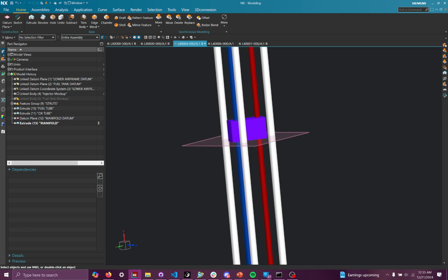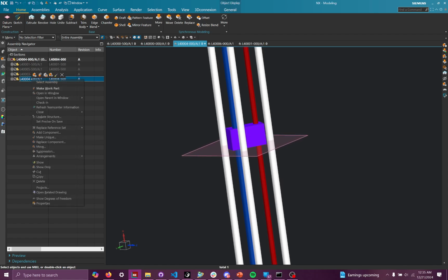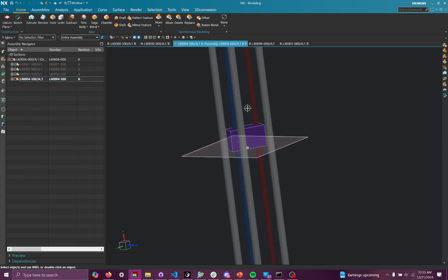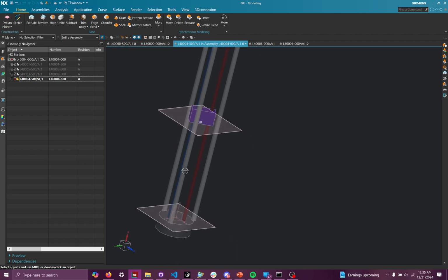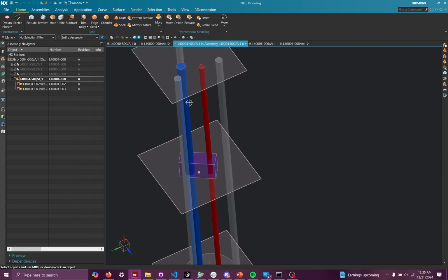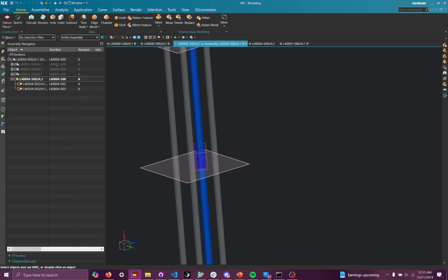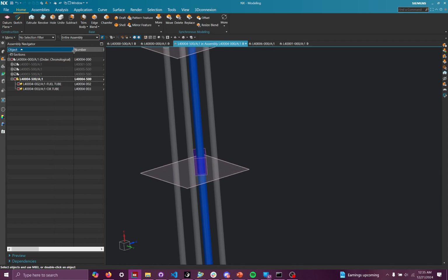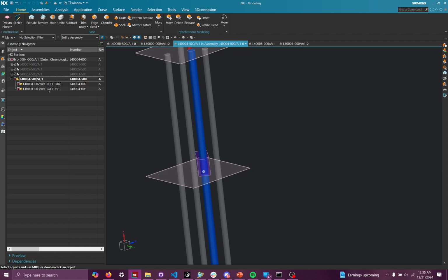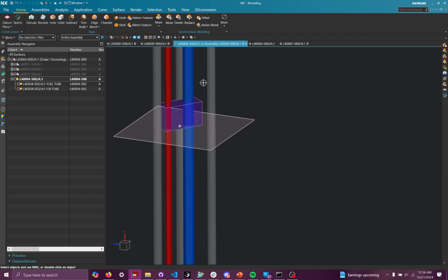So let's go into the Assembly Navigator tab. Let's move into the assembly file for lower plumbing. Let's make it a work part. You see everything else gets grayed out, besides these two tubes, which were already populated and already have their own part files, fuel tube and aux tube. So let's make one for this manifold here.